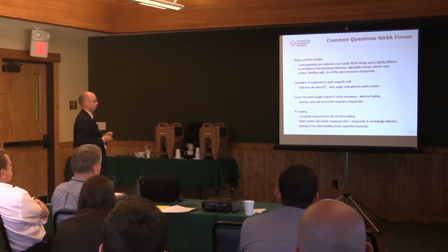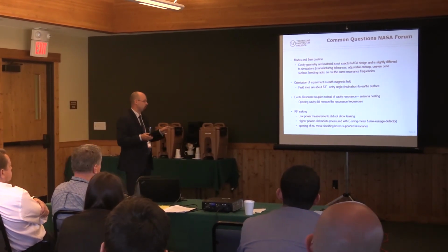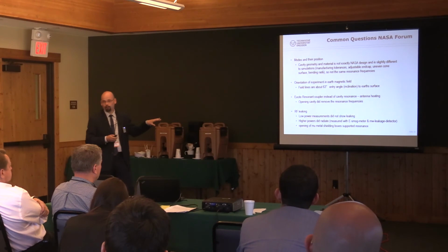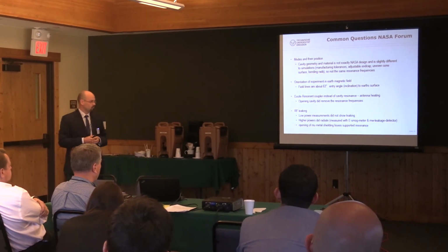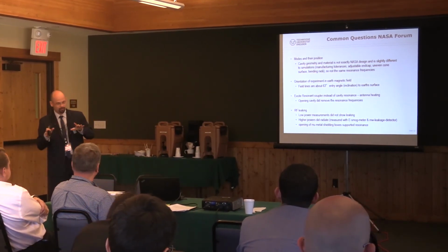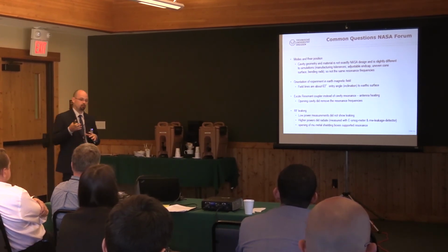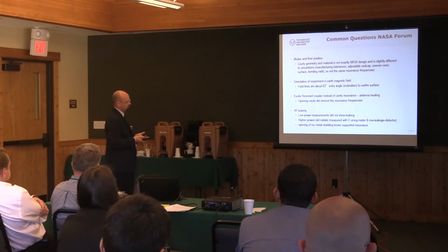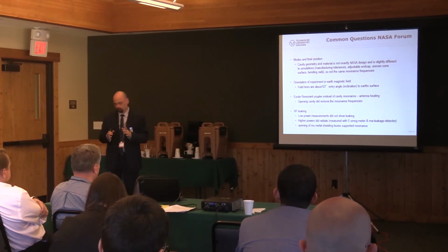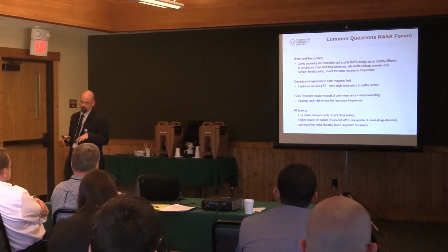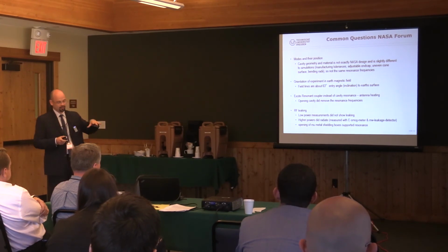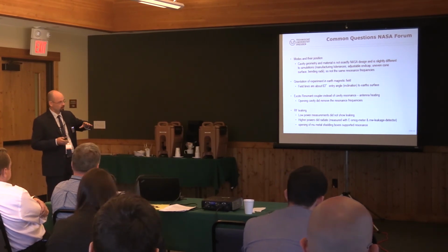So, who knows? Another point mentioned was the problem of RF leaking. We did some measurements, let's say calibration tests, outside of our vacuum chamber, and of course we did our measurements inside of our vacuum chamber. Low power measurements did not show any leakage at all outside of the vacuum chamber. Higher power levels instead showed a weak leakage.